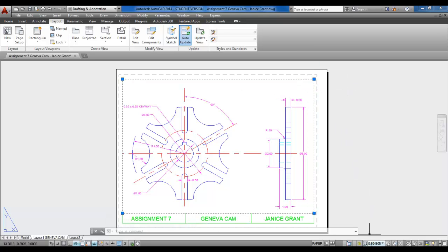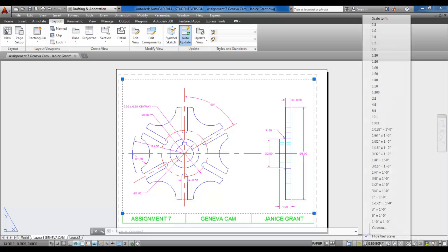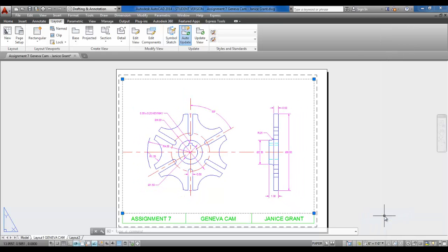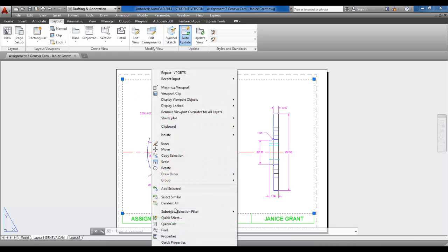We do have at the bottom right corner these numbers that represent the scale. They're asking us to set it up as 6 inches equals a foot, which is also a custom scale of 0.5, or kind of half scale, and that'll set the scale. In the book they're showing us a different way back in the properties palette. So you can right click if you'd like and pick properties.